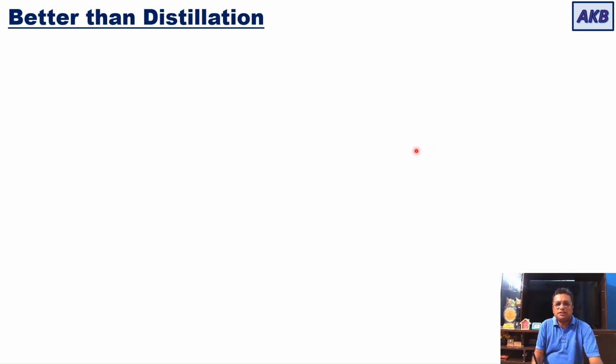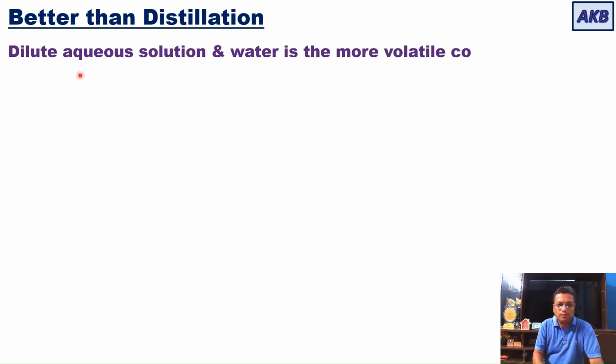Then let us look at some applications where liquid extraction is better than distillation. There are few applications where you'll find that liquid extraction is better than distillation. So when is this true? In case of dilute aqueous solutions, where major component is water, plus when water is the more volatile component, that means you need to vaporize water.